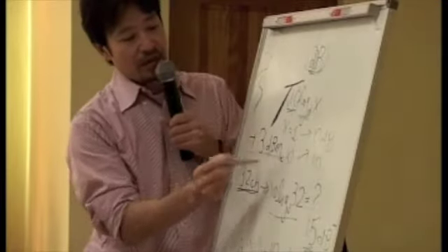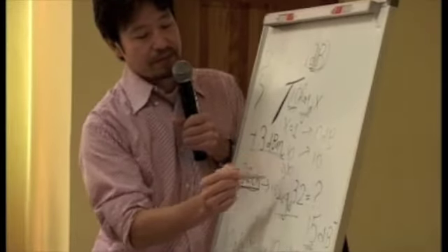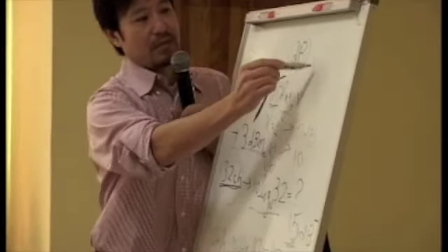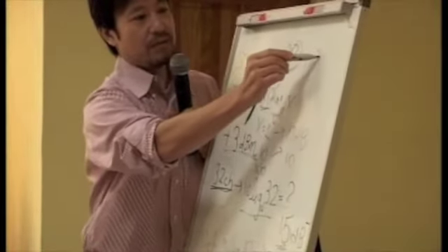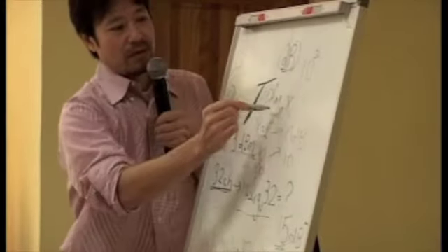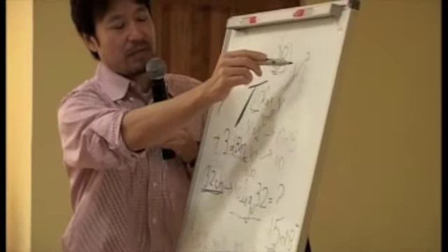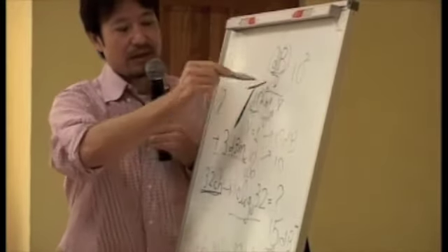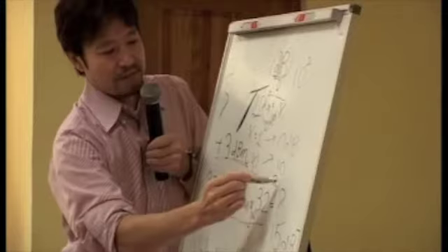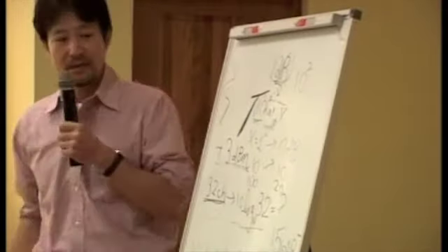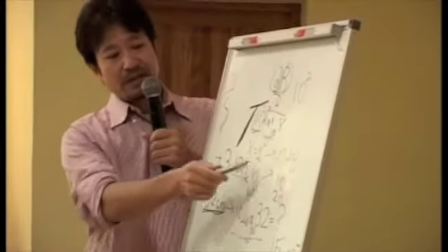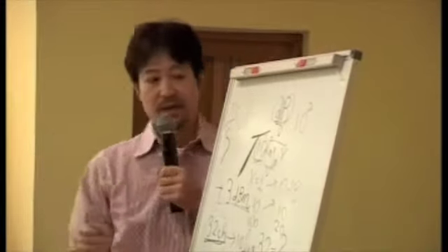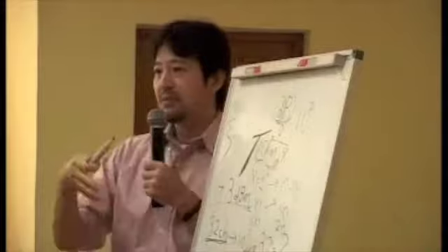If x equals 100, that is 10 to the power of 2, so the logarithm is 2, and 2 times 10 is 20. So 0 dB means the same value, the same amount. 10 dB means 10 times larger.